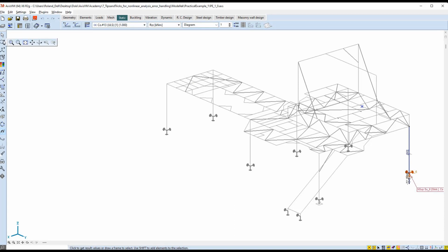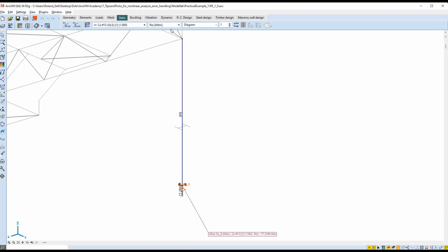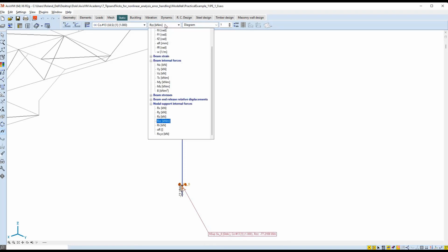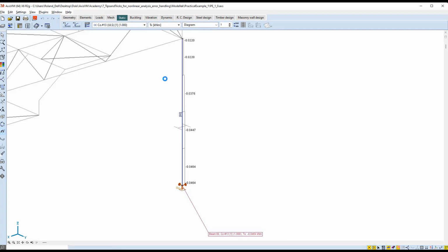We can see the big difference mentioned by the user. The support moment RZZ is more than 100 times higher than the torsional internal moment of Tx of the beam. It highly violates the moment equilibrium.